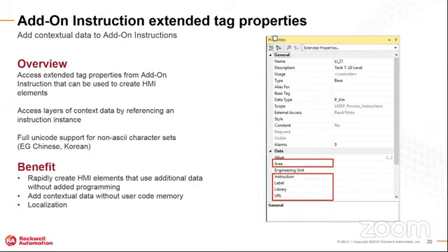Now, this idea for including additional data started back in version 21 of Studio 5000. So it's a continuation moving on from here. But you would find this very beneficial if you had things such as engineering units that you wanted to include into your add-on profiles, or even placing URL links or additional information from the label or library.